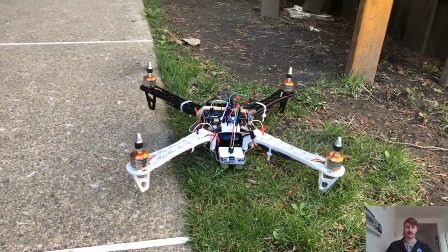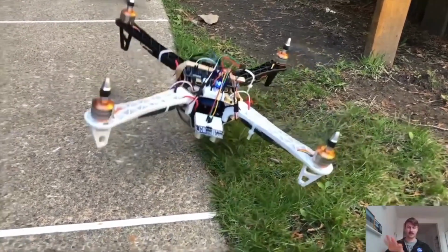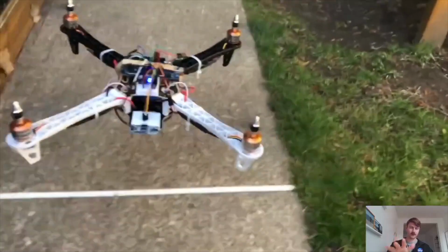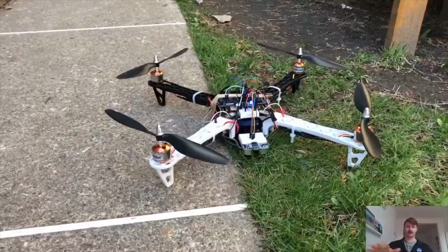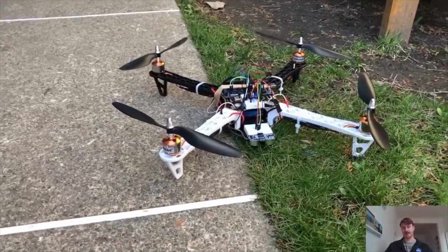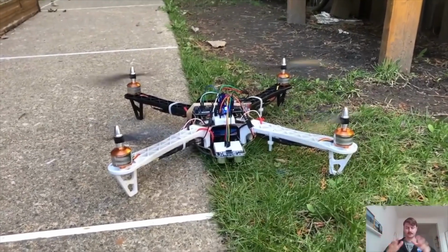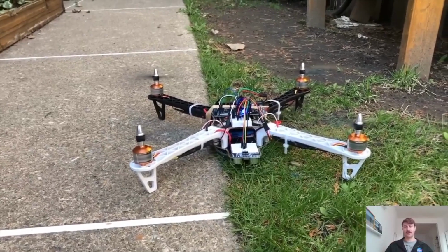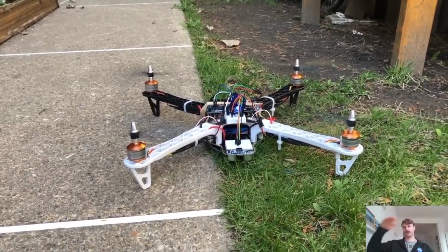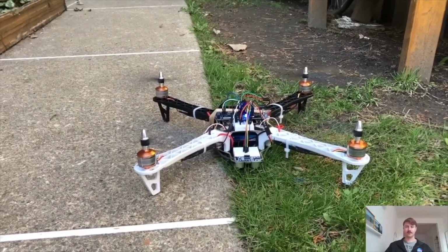So one more time, it takes off, it gets a little unstable, and there's the P controller correcting itself, and then it starts to drift to the right, and so the I controller kicks in and starts to try and correct that drift back to the left, but ultimately it's not high enough to have a really clean flight pattern, and because of the enclosed space limitations, the higher up it is, the further it can travel if it drifts, so that was just not feasible for this testing.